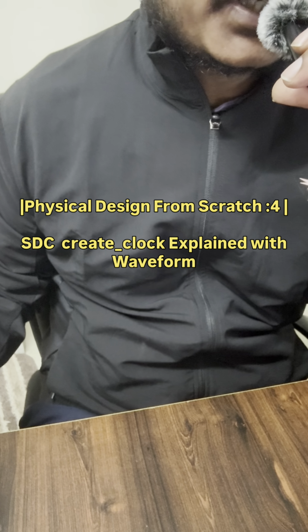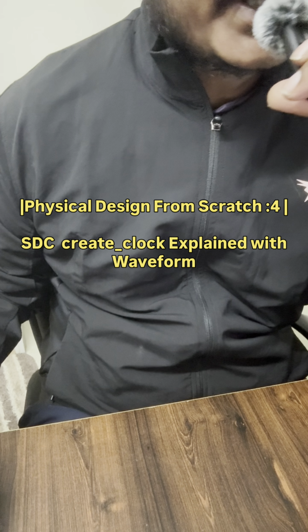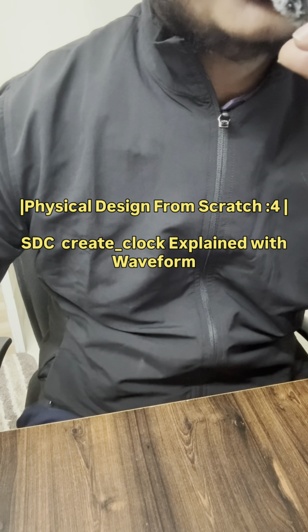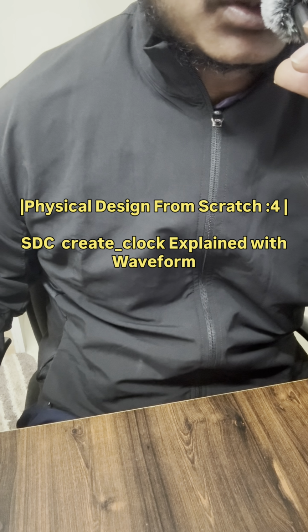Hi everyone, today's topic is SDC constraint. In this, we mainly focus on one constraint, which is create_clock. In static timing analysis, or timing analysis, the first and most important constraint we define is the clock.